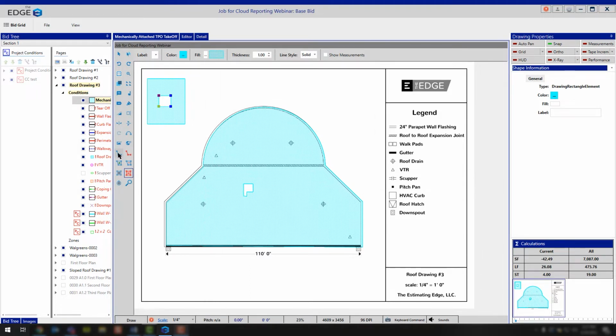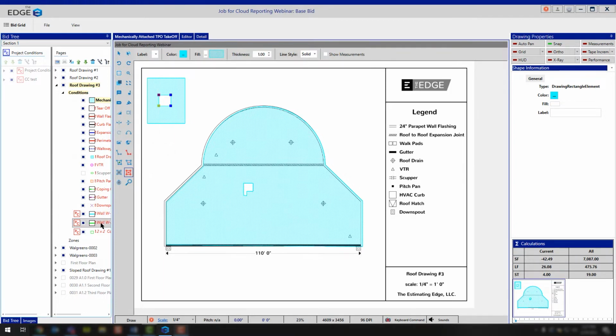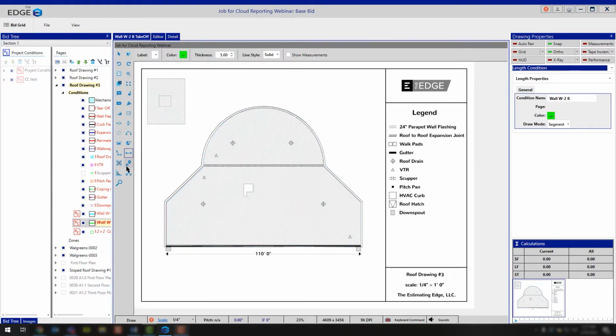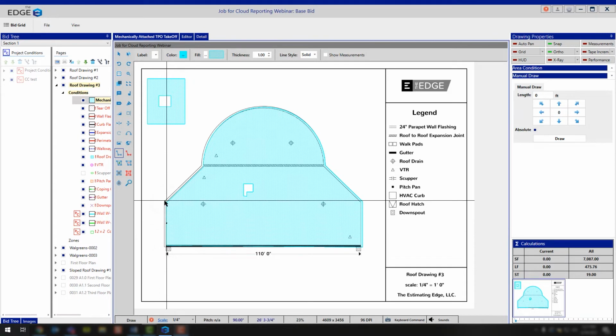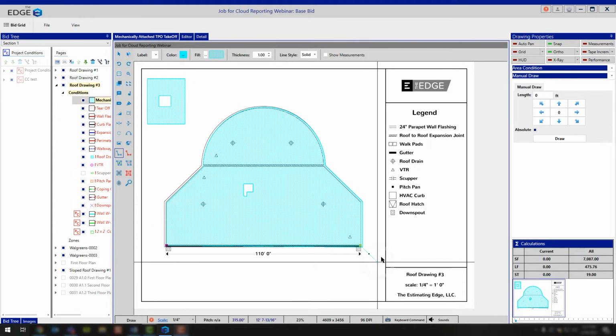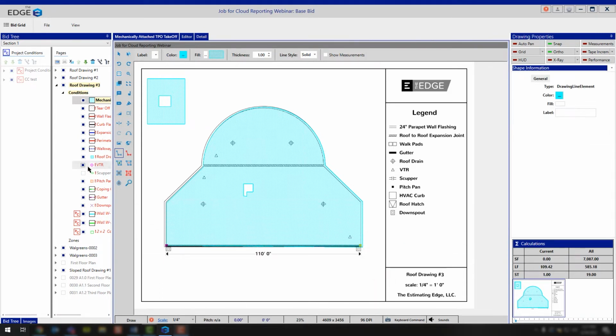In some conditions, you will have additional tools available, lineal measurement tools, or you'll run into count tools if you're looking at something like the drywall conditions. You'll notice that you have count icons available for you. Ultimately, just left click on those and use those options. If it's anything lineal measurement, you can left click on the lineal measurement and then just go and measure where you need to add that lineal measurement ability.